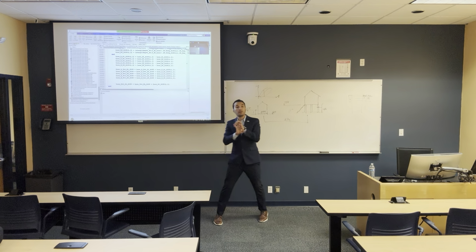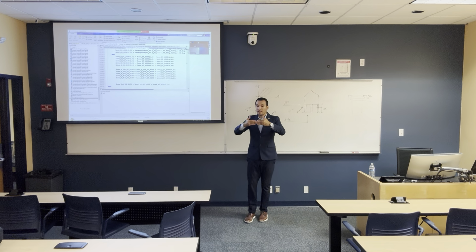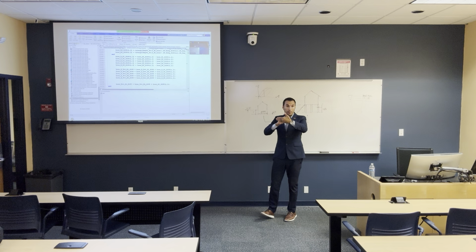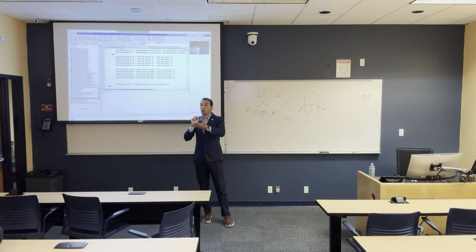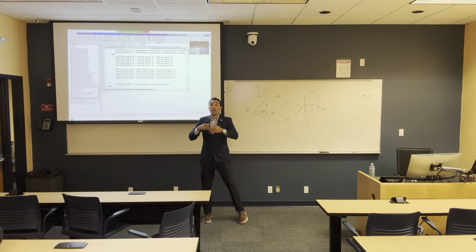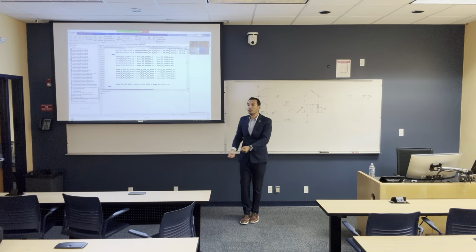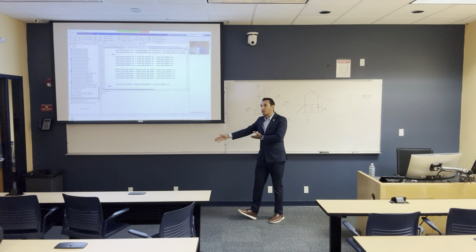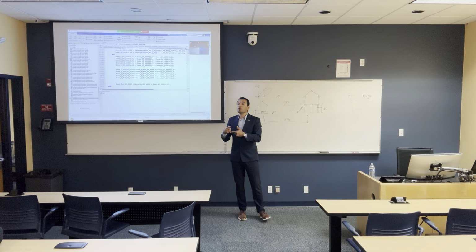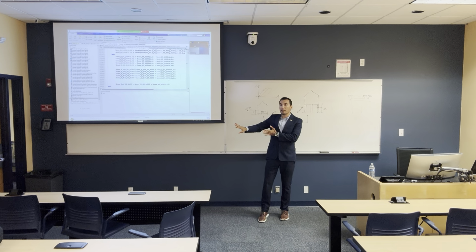When I use a levee, this levee is going to dam the water and protect you, so it decreases the flood depth. Rather than having a flood depth of 5 feet, you're going to have 2 feet or something. That's a hazard. If you build a retention system that takes from the water that goes downstream, we are decreasing the hazard. If we are using pumps, we decrease the flood duration. The flood duration is also a hazard itself. So all these are hazard mitigation measures.